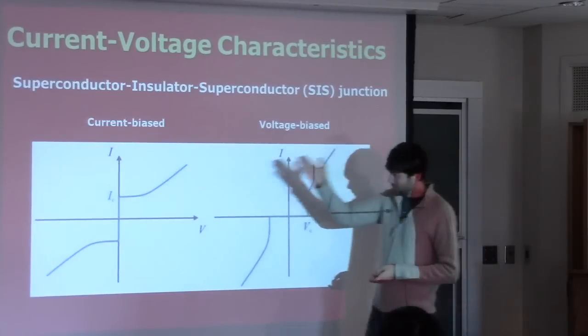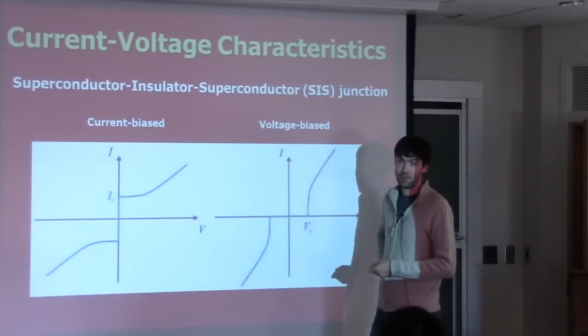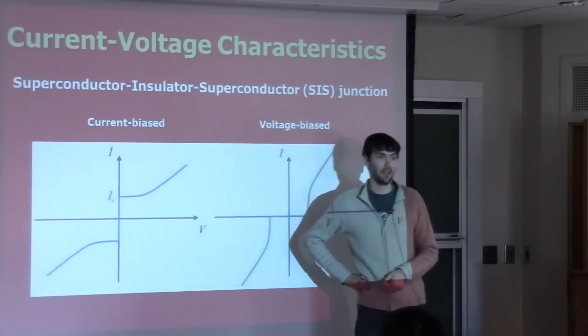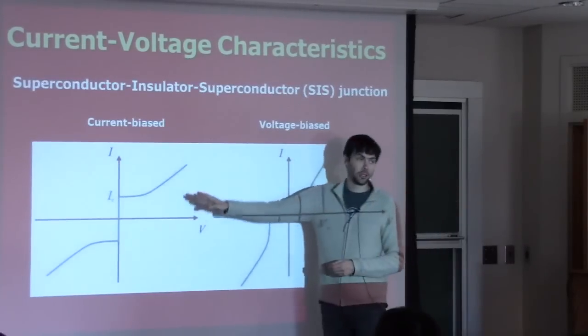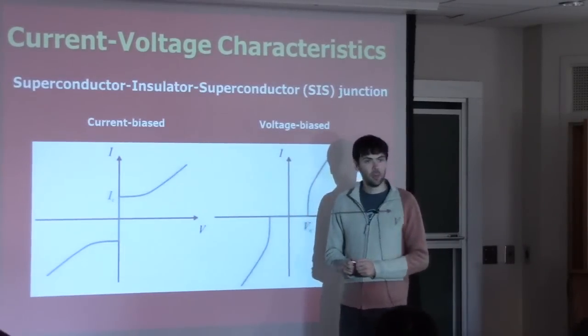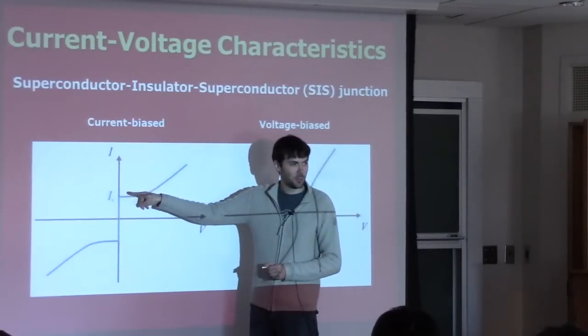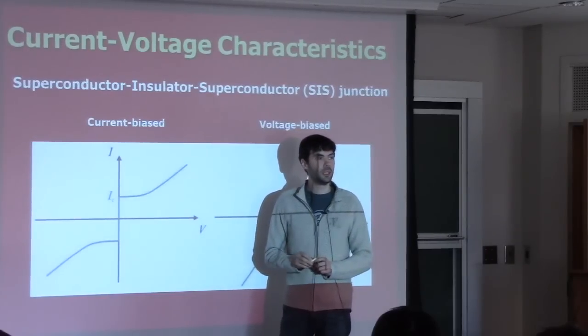And when you see something like this in your data, especially for the first time, you can be very excited. You are clearly not measuring Ohm's law. The two measurements are similar and different. In the sense that there will be a critical current, they are similar. But in the details, like the shape of this cusp, or whether there is a hysteresis here or not, those are very different.